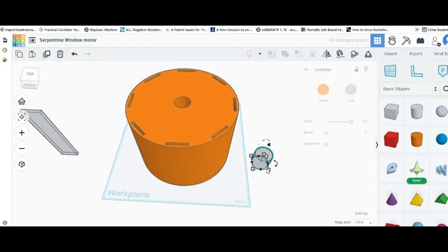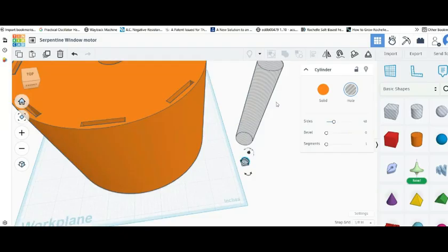So the diameter of a penny is 0.75, so we'll make it 0.76 inches, so the pennies can just go in there. And this is 4 1/8. We need them to rest on the bottom, so we make this 4. Now I want to do one other thing. If we put the hole there for the pennies, and you put all the pennies in, they can get wedged in there. And then what do you do? You're out like 20 cents, and you're stuck with all the pennies there. So I want to put a hole in the bottom and the center of this so that you could take a little screwdriver and just push them out if they're wedged in there. So that's what this is.